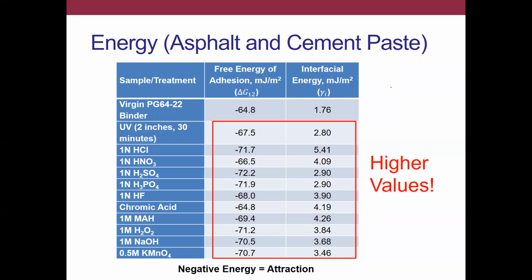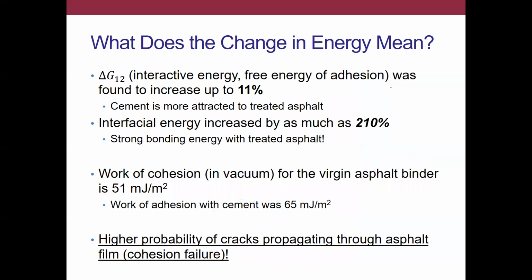So this does prove that these different oxidizing treatments would enhance the chemical bond between the asphalt on the RAP and your hydrated cement. What this tells us is that this energy of adhesion can increase by up to 11%.